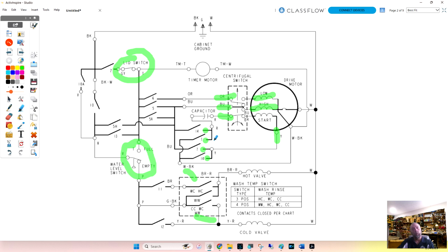And on the old washing machine, the washer had two solenoids on the transmission. One was for agitate, one was for spin. And the timer switch numbers were 7 and 14.